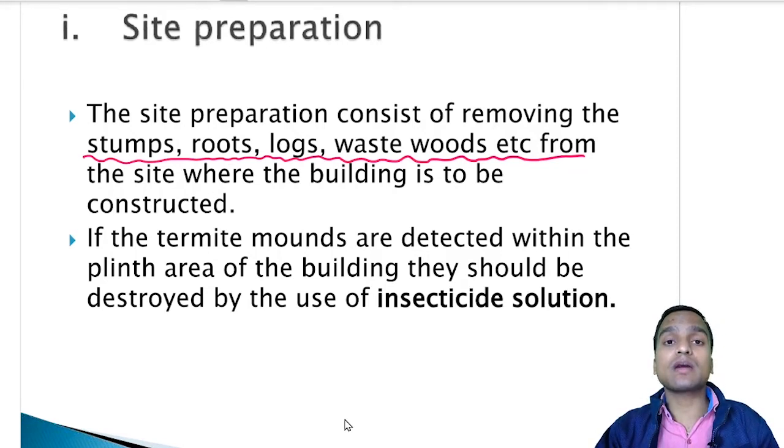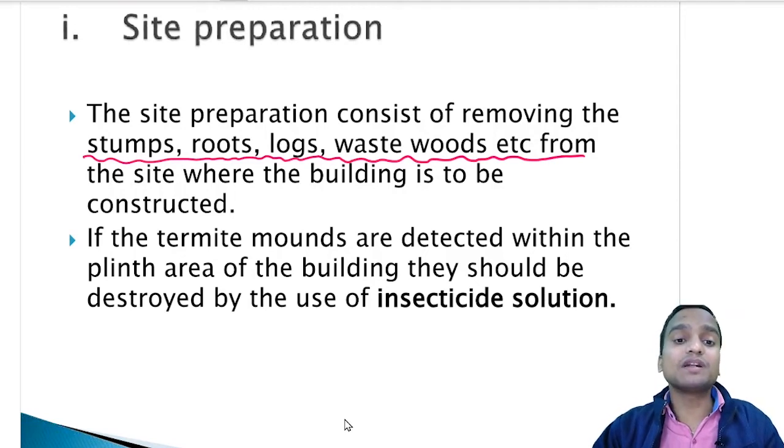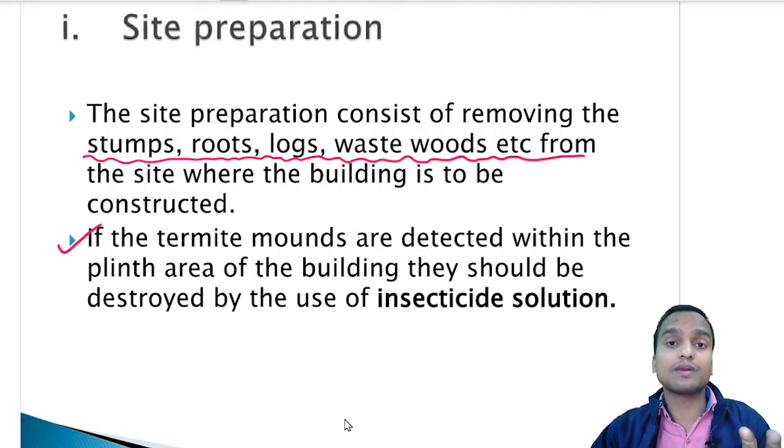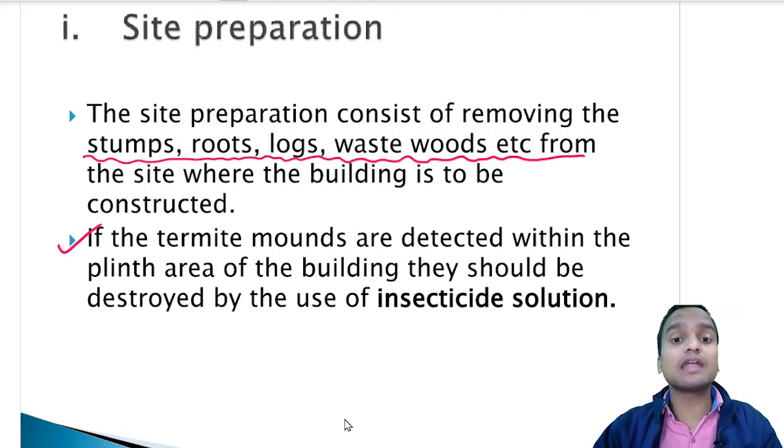Now many a time what happens is we leave these organic materials in contact with the soil, which is in contact with the foundation. So that becomes a potential source of termite attack or infestation. All right. So that's why site preparation is very important before construction. And if termite mounds are detected, these mounds being the nests where the colony of termites lives, within the plinth area of the building, they should be destroyed by the use of an insecticide solution. Okay.